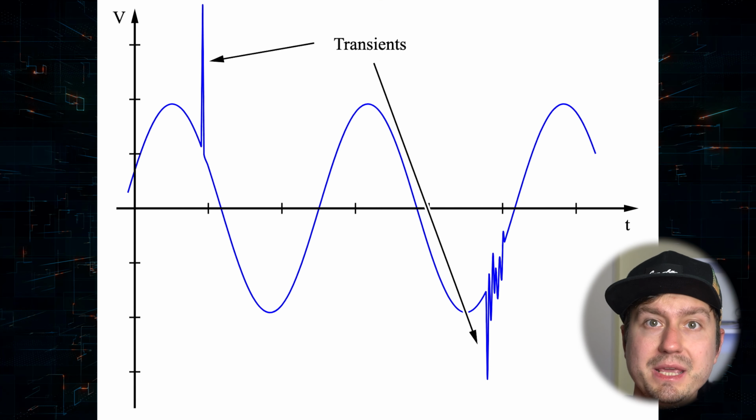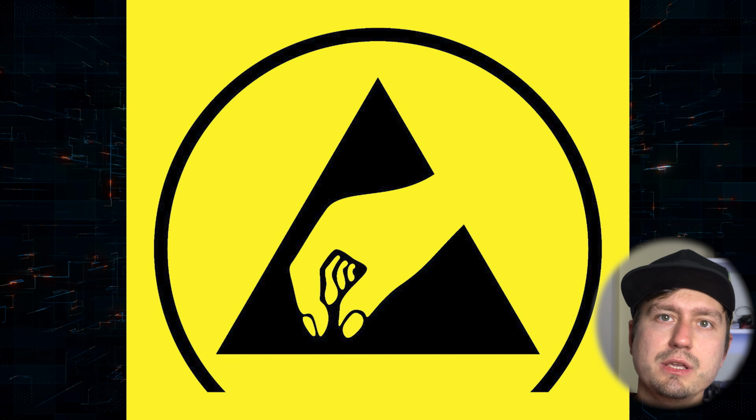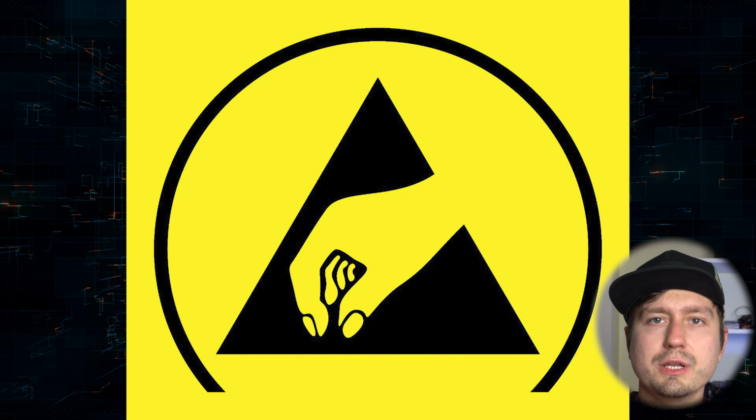The difference between transients and surges is that transients are short in duration, so those would typically be very fast and high spikes on mains voltage, which are quite similar to ESD spikes that we would get from, let's say, just touching a microcontroller, and I talked a lot about ESD in another video. The transients on voltage mains typically have a different source of origin though, as they would normally come from either a noisy power supply that generates a lot of inrush current, or they would just be present on the mains because of cable dragging and things like that.